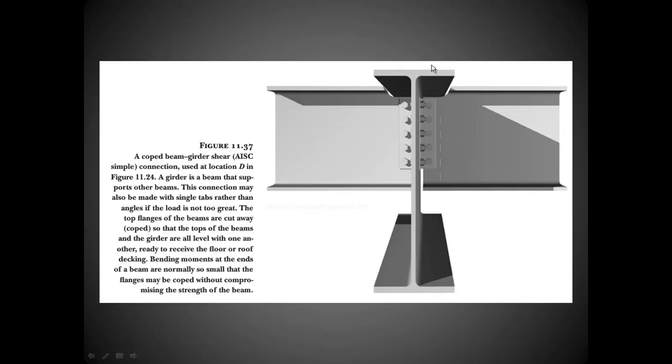So if we have a floor that is being poured on the top of this configuration, we have steel that's supporting it continuously all the way through. Otherwise this would be lower. So putting a cope on those cuts is fairly common.